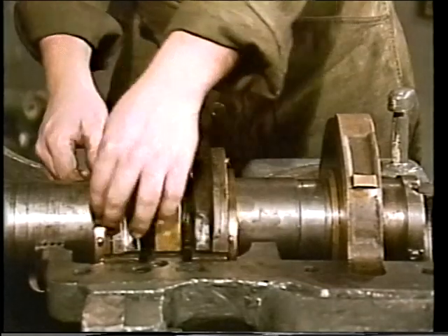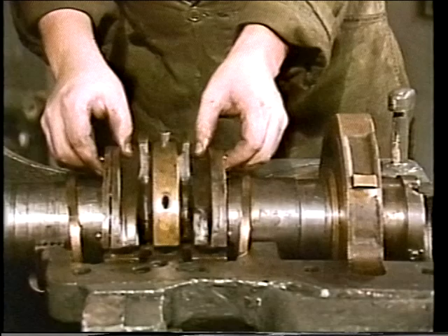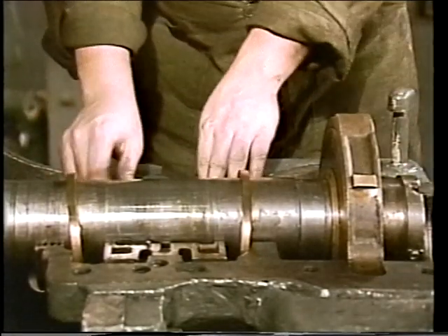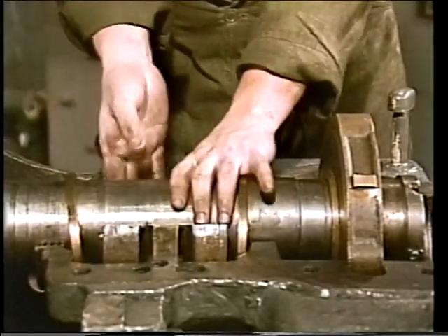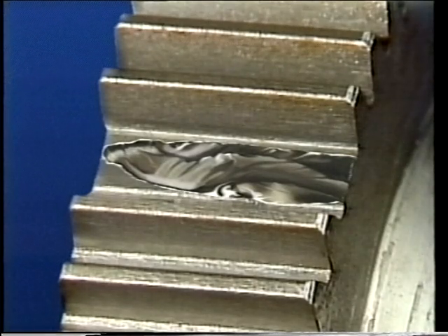Sometimes journal bearings are not properly aligned with the shaft that they're supporting. As a result, they wear in an oblong manner. When the shaft rotates in the oblong area of wear, instead of in the normal circular pattern, vibration can result. Vibration can also result from defective gear teeth. Generally, when a gear's teeth become worn or broken, it can no longer mesh smoothly with other gears. In many cases, the rough meshing action produces a distinct vibration.